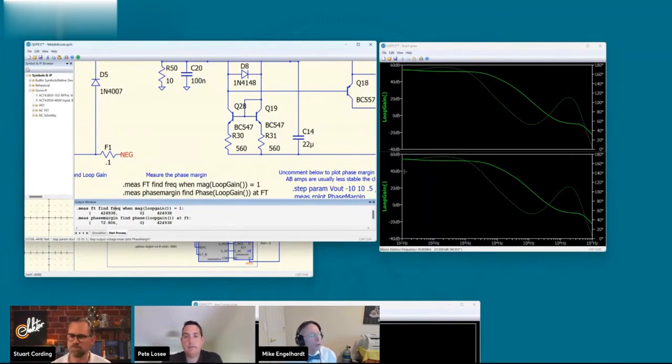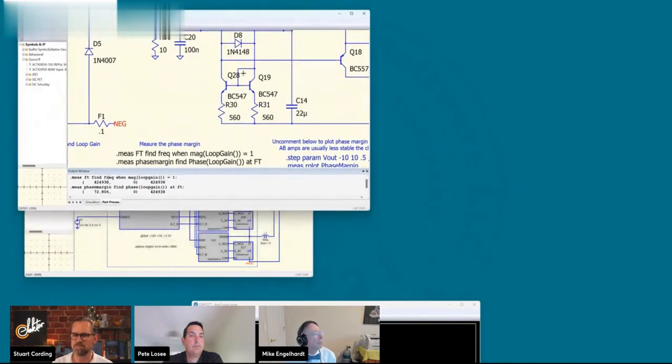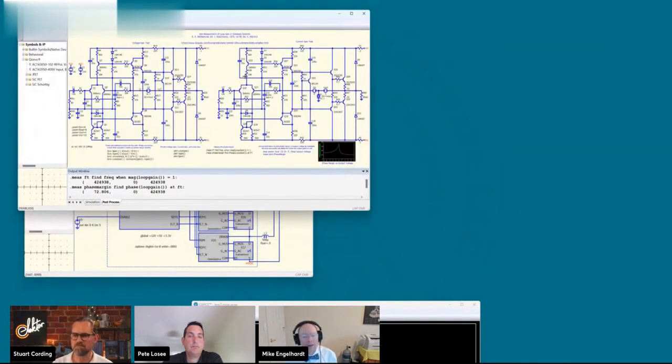All right. So is that right? Let's just, yeah, 450 kilohertz. It's a real good audio amplifier. Exceedingly low harmonic distortion. But, you know, the phase margin is basically not a good quantum number. It kind of varies all over the place because in an AB amp like this, as you switch from the high side, the low side to running both, the phase margin varies dramatically.